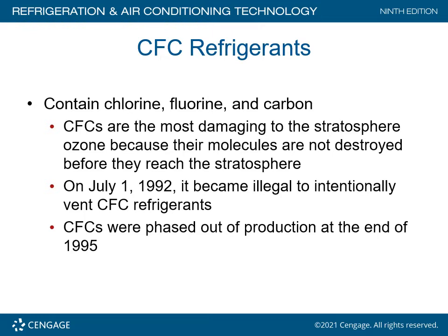CFCs are the most damaging to the stratospheric region ozone because the molecules are not destroyed before they reach the stratospheric region. On July 1st, 1992, it became illegal to intentionally vent CFC refrigerants. CFCs were phased out of production at the end of 1995, beginning January 1st, 1996, and are no longer available. There are very extremely limited amounts of CFCs still in use around the globe, including the United States.